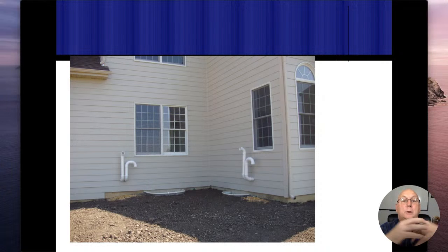So on these two, we have 2 different furnaces. What's folded downwards, that's my exhaust. And then what's pointed straight outward, that's my, I take that back, I'm sorry. What's pointed straight outward is my exhaust, and what's pointed down, that's my intake. I got those flipped around. So that exhaust, as I'm blowing air away, that's what needs to be a foot away from those windows. And I think I'm close, but I don't think I'm close enough to where I'd call these out.